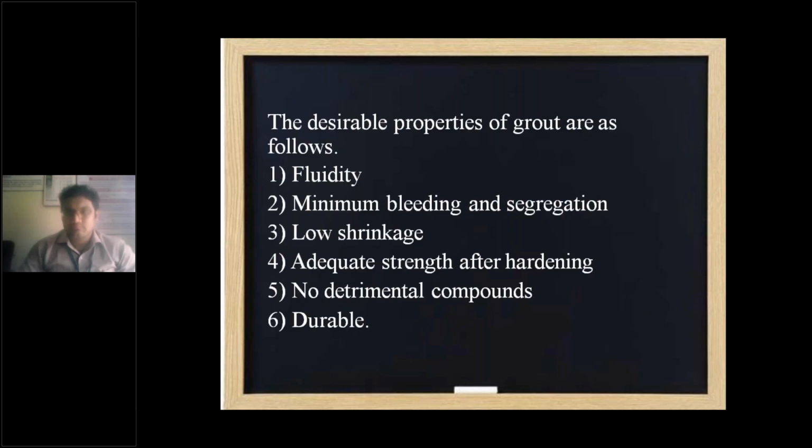Desirable properties of the grout. Here grout should have these properties. One is fluidity. It should be in a position to flow from one end to the other end freely. If it is tight, what happens? It is not having good workability. The fluid can't flow from one end to the other end. So it should have good fluidity.